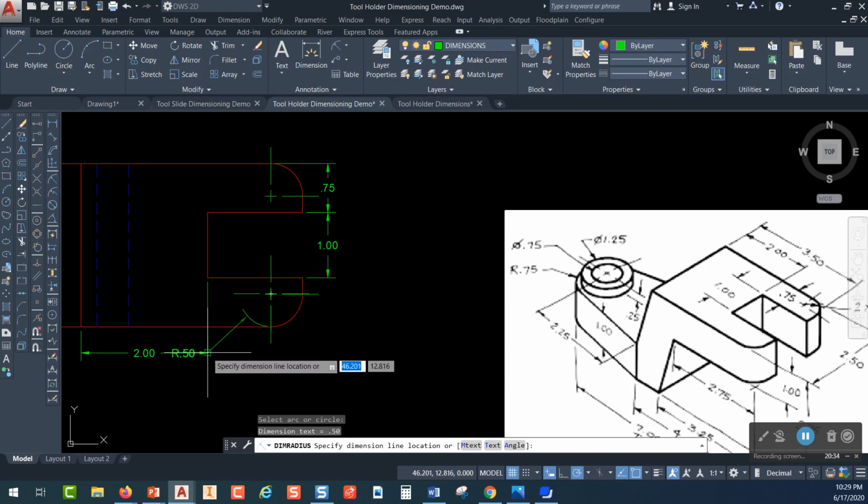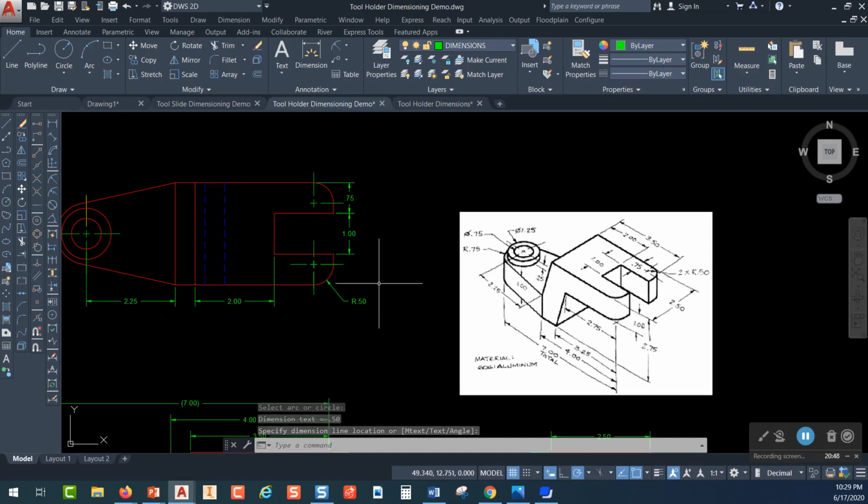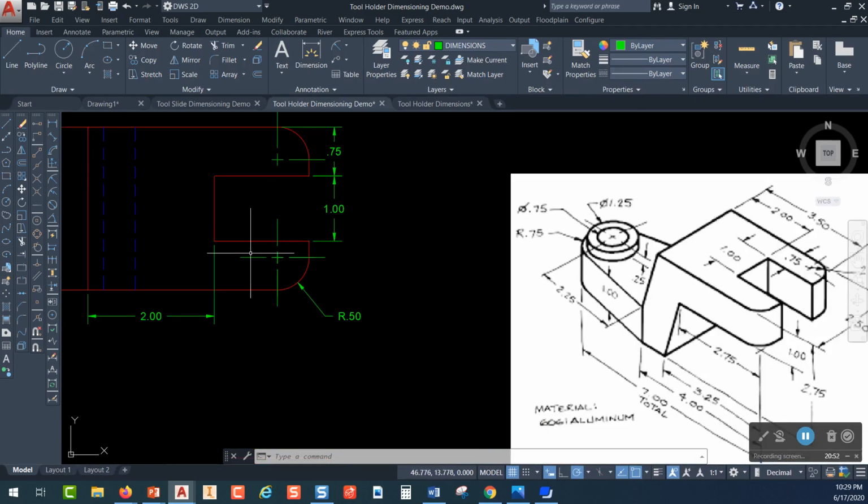Now, if you want to line it up, you could go over here and just park on that endpoint and acquire that. You can see that dotted line that's coming across right there. I could just pick right there, and I'm just keeping everything lined up, trying to keep it as consistent as I can. Now, when I use the radius command, it adds some extra center lines. You can see that because they come in with their own center lines.